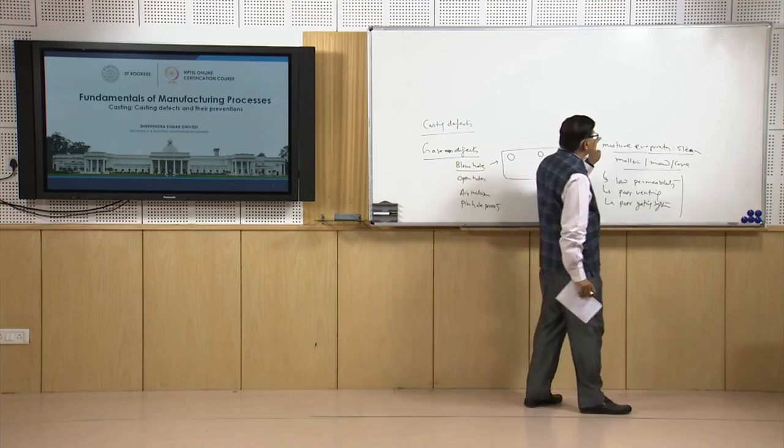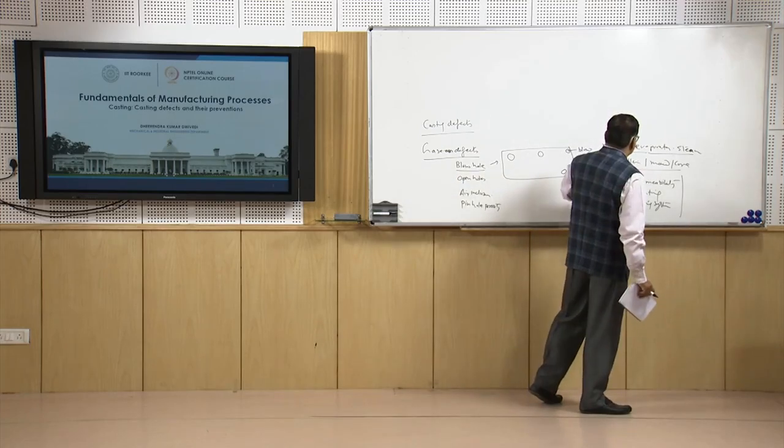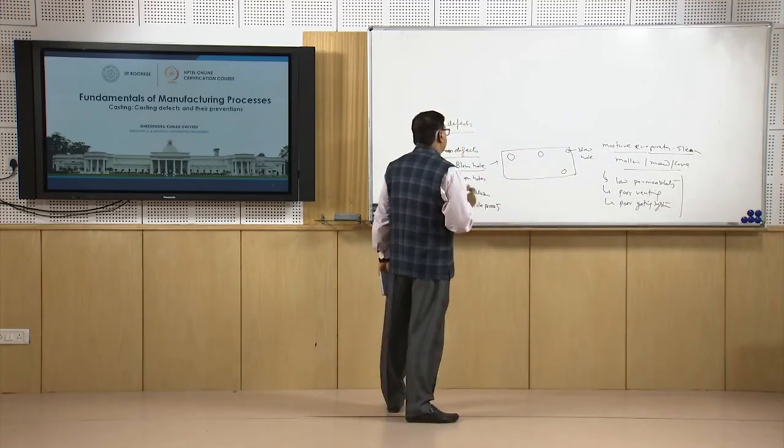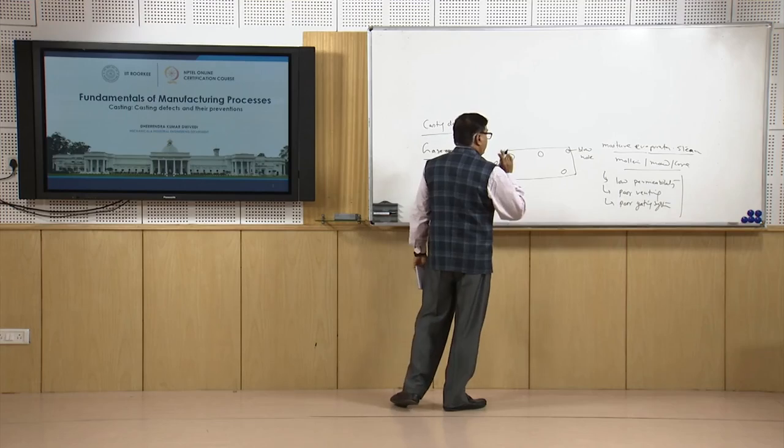Basically the primary reason is the moisture steam generated, and that steam is not able to come out of the mold cavity, so it remains in the casting.